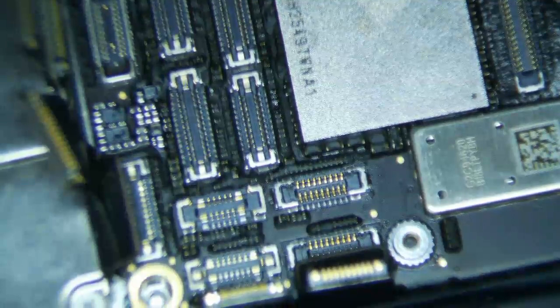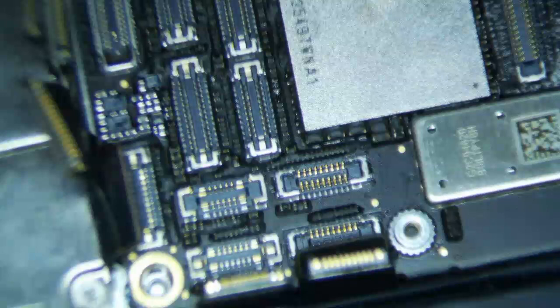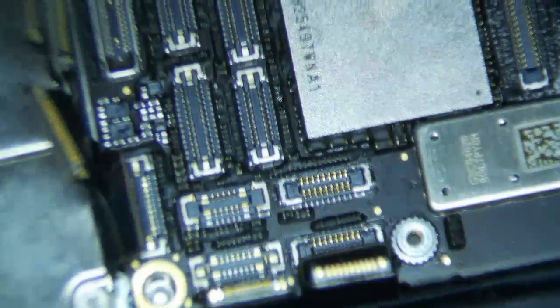So what that tells me is that it's most likely not VDD main and more likely VDD Boost, which is a sub power line of VDD main. Okay, and I think VDD Boost is related to the audio, but I'm not positive on that. Anyways, this is an iPhone 11 Pro.